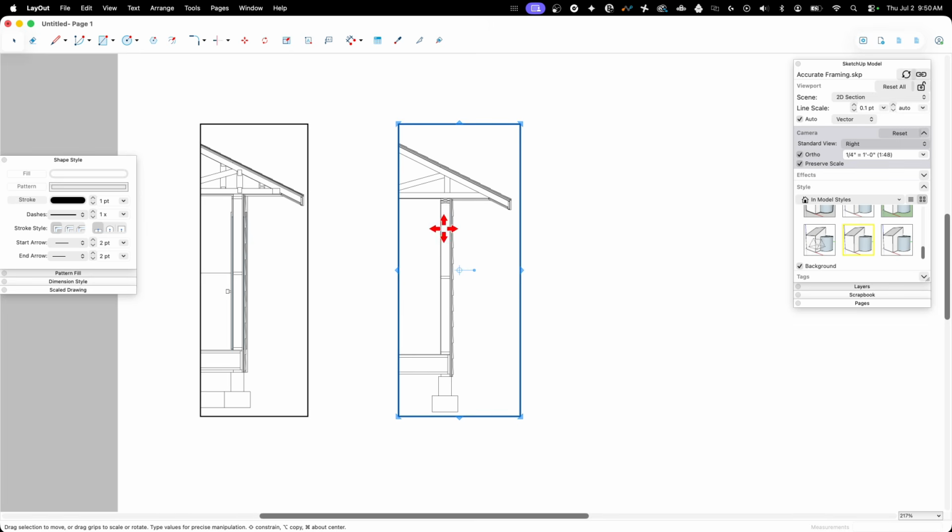Downside to this one, of course, is that because this is just line work intersected with a face, these aren't connected to anything. If I was to come in here and change my floor joists to floor trusses or something like that, that would drastically alter my profile, this would still look exactly the same. I'd have to go through to re-intersect and get that to change in order to reflect that, have that show up in my section cut.